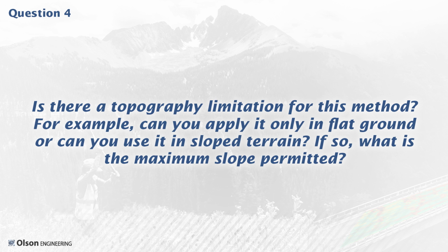Okay. Is there a topography limitation for this method? For example, can you apply it only in flat ground, or can you use it in sloped terrain? If so, what is the maximum slope permitted? So you can use it in undulating and sloped terrain. The only thing you need to be aware of is you need to have a receiver density high enough that you're actually characterizing the shape of the slope. And as far as a maximum slope permitted, as long as you can stand on it and put a geophone in, you should be fine.